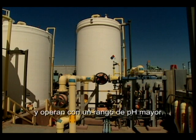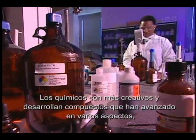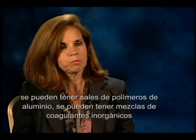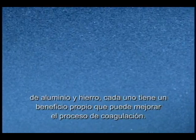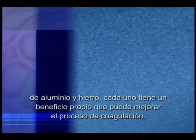The chemists have gotten more creative and they've developed compounds that are advanced in various ways. You can have polymerized aluminum salts, you can have blends of the inorganic coagulants, the alums and the ferrics. They all have their little benefits that will improve the clarification process.